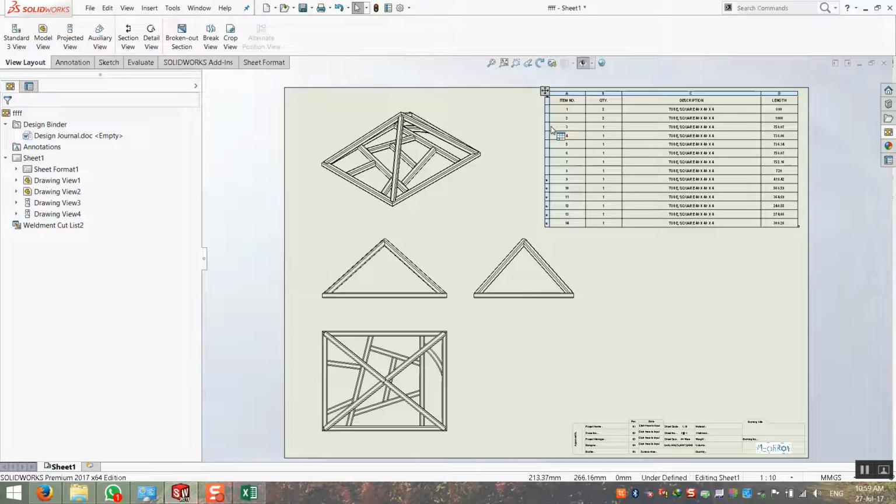Are these views satisfied for him to know and understand what you need? If he will see this, okay, are all the dimensions you need clear according to that or no? For the box, it's okay. But for another shape, you need to put more. For this one, it's okay. But now, if I will add something, I will add a hole at the top, and this hole will be through.